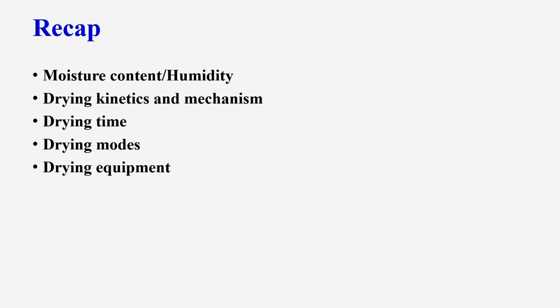There we discussed what is moisture content or humidity, then how the drying process is done, maybe at atmospheric pressure, under vacuum, or by freeze drying. We discussed the mechanism of removal of moisture through evaporation or directly through sublimation in the case of freeze drying. Then we discussed simple drying kinetics. We assume the rate of drying is directly proportional to the change in moisture content, minus dx upon dt, and